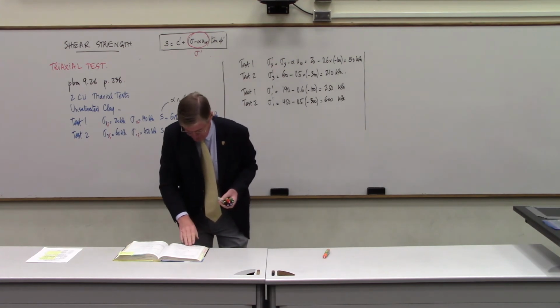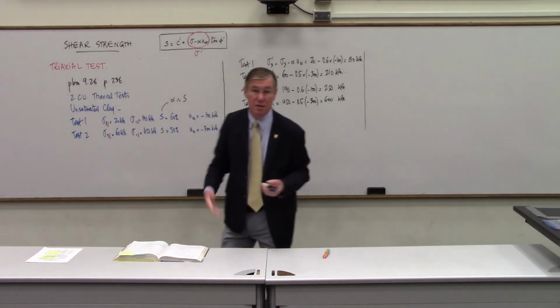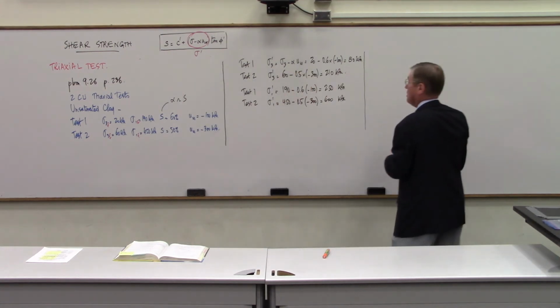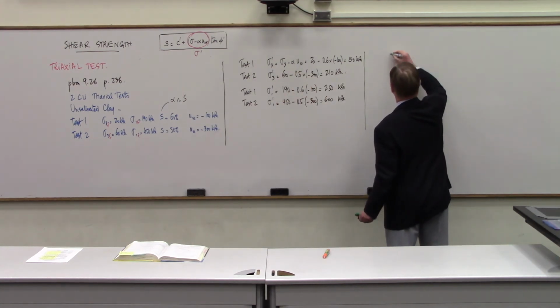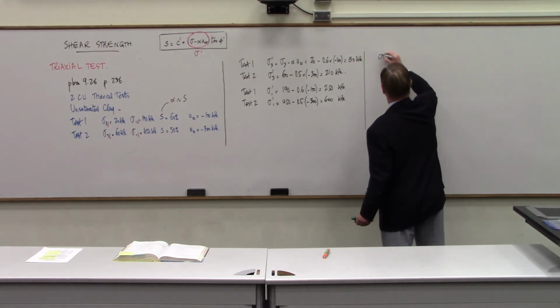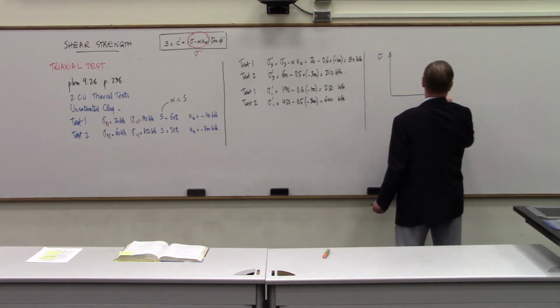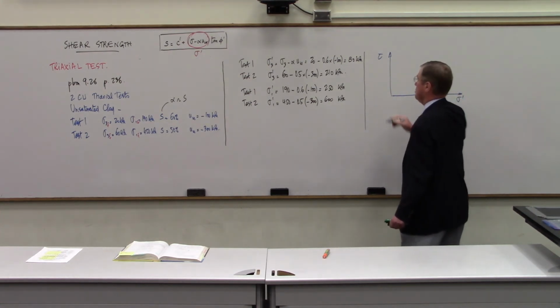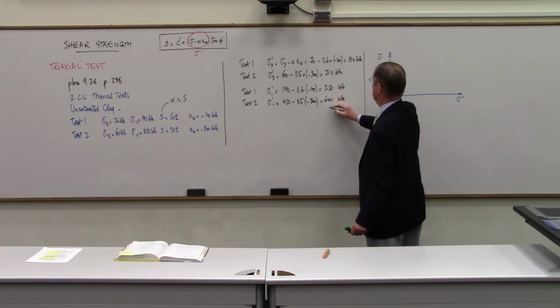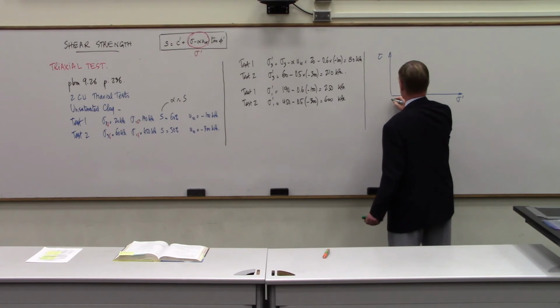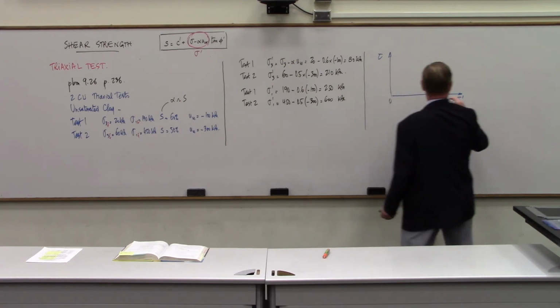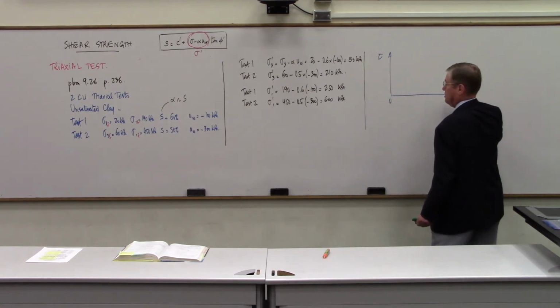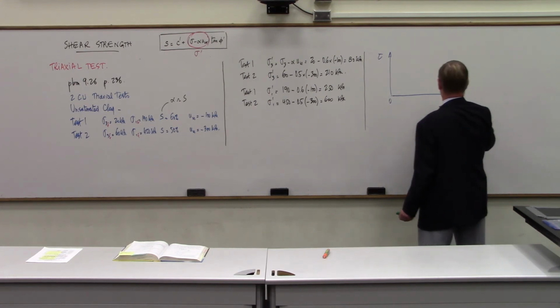Draw the Mohr circle at failure in the tau versus sigma prime axis. So we're going to do that. Here is the tau, shear stress, versus sigma prime, set of axes. And we got numbers that go all the way to 600. It looks like the largest value. So we're going to go from 0 to 600 right here in kPa.